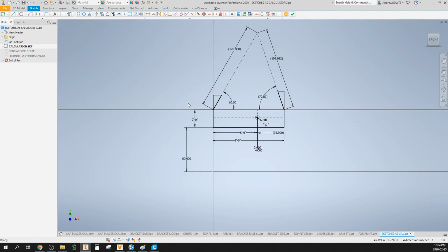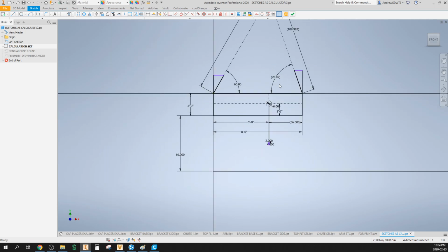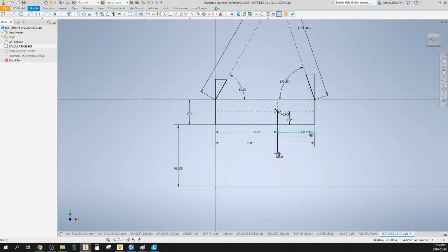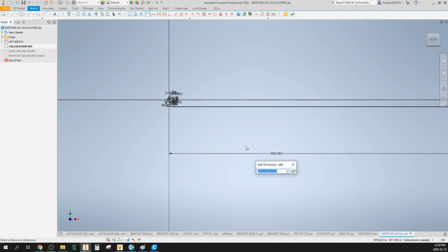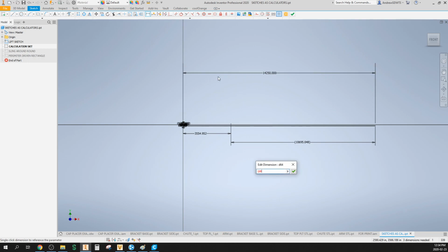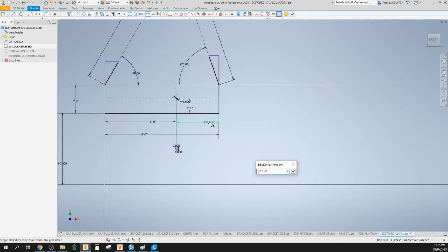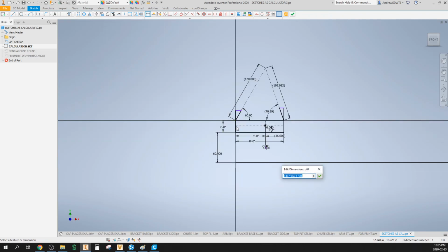Now I just need to figure out how much of that load is picked up by either side. So I start with the vertical component of each, and just by the moments needing to equal 0, I know that the full weight of this thing right here at 3 feet is going to be suspended by the vertical component over here at 8 feet. So I can just make that a function. The total weight, 14,250 pounds, times this distance, and then divide that whole thing by the overall distance, gives me my vertical component for this sling.